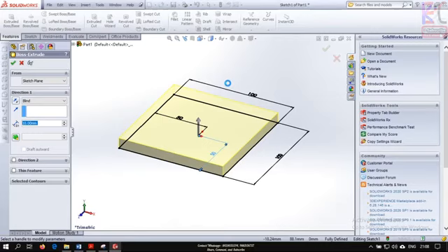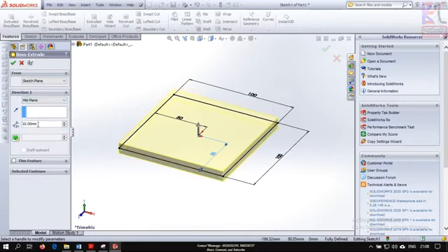That doesn't mean that you have to select the command first, before what you need to do. You could select the command after the sketch also. That's what I want to show. After doing the sketch, there are three things: mid plane, up to body, and so on. So what I can do, I'll go for mid plane. Fine. And how much? I've selected 100 mm.